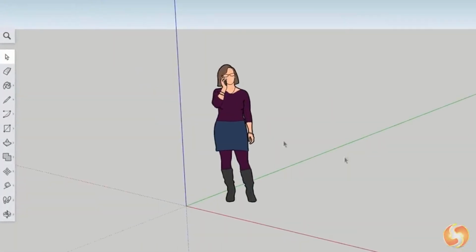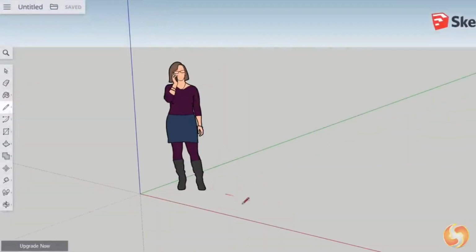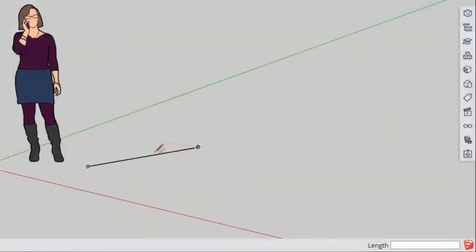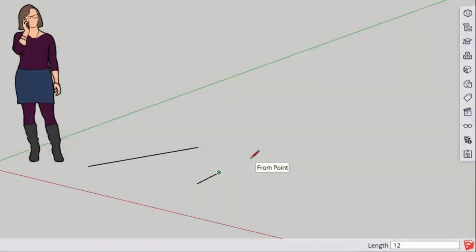To draw any element, you can use the tools on the left side, some grouped into a single button. Once a tool is enabled, you can define object points and sides by either clicking on the preview or typing precise values with your keyboard in the box in the bottom right corner, applying with the Enter key.